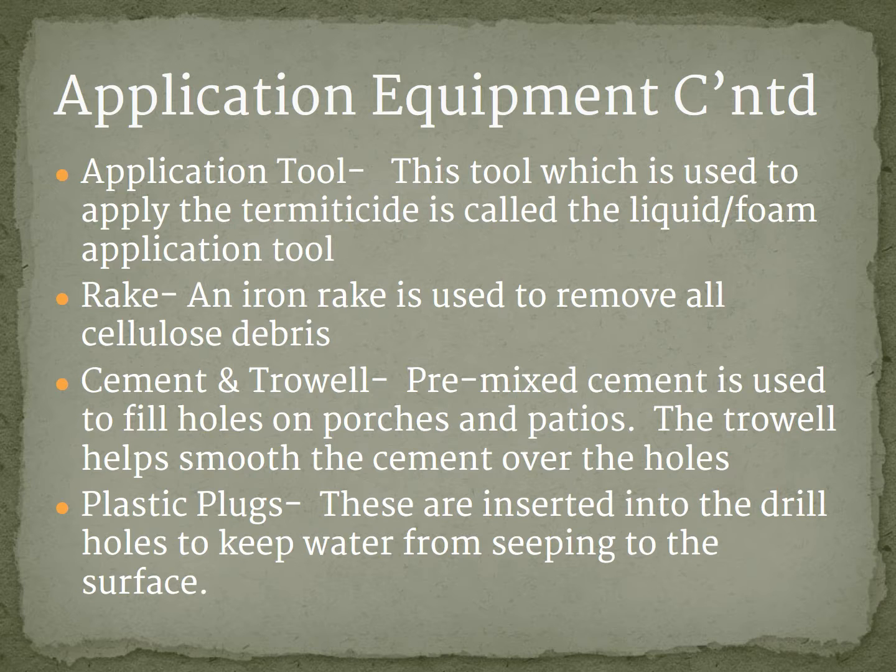And again, the next line we've got here is the plastic plugs, and that's just depending on your company, but if you're using like the 5/8 inch holes or even 1/2 inch, you're definitely going to want to use the plastic plugs because the cement will just get swallowed up by the holes.